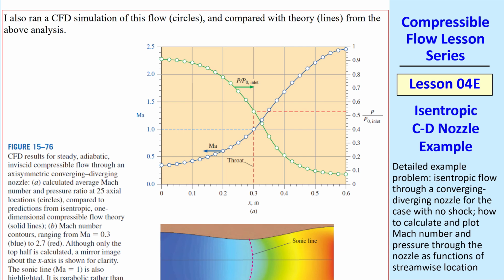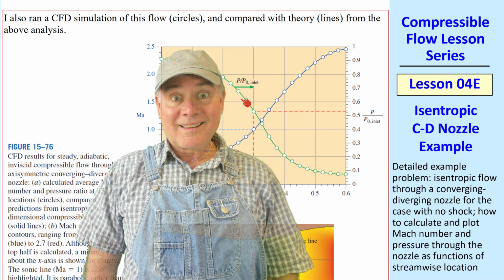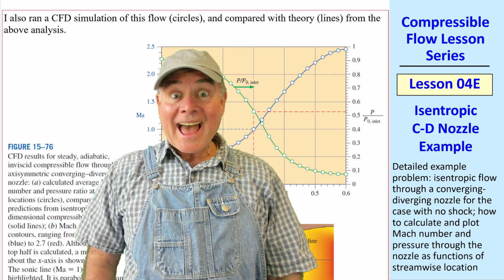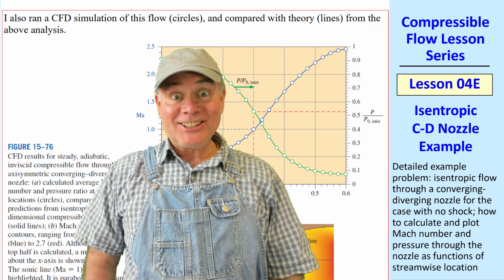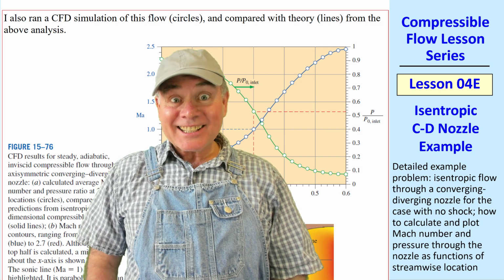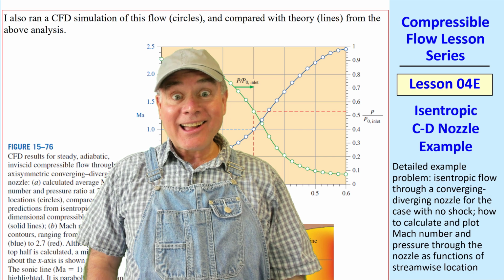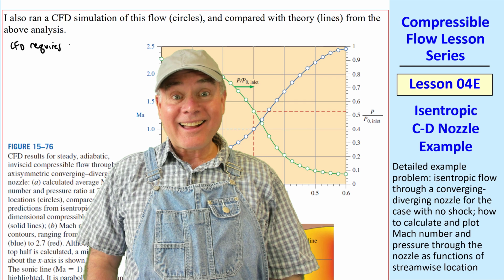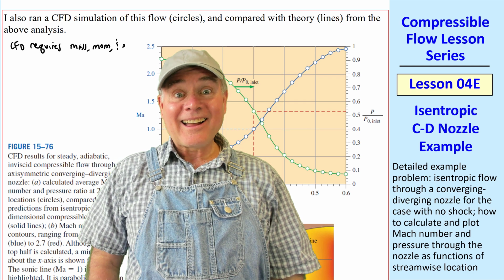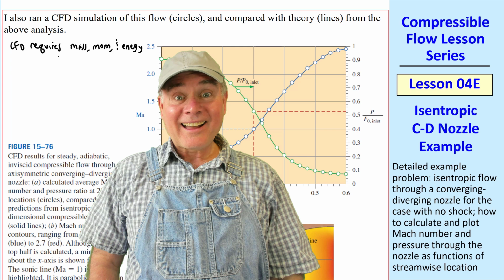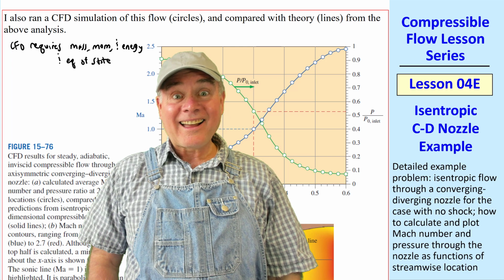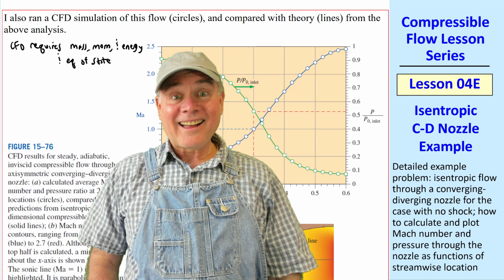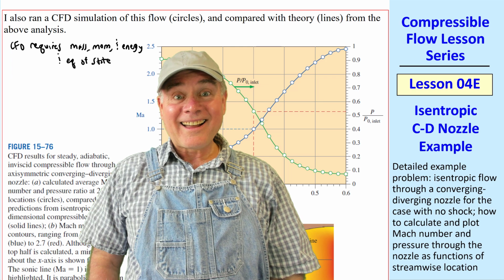I ran a steady CFD simulation of this flow as indicated by the circles and compared them with theory as indicated by the lines. Well, I never knew you could use CFD for compressible flow. Well, Dude, you can, but unlike incompressible flow, CFD requires mass, momentum, and energy equations, and an equation of state, which I chose ideal gas, and I used ANSYS Fluent for these calculations.